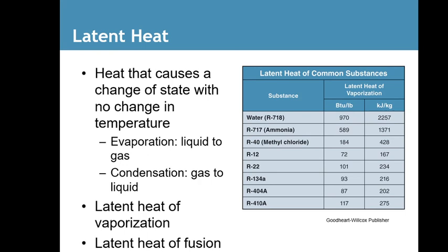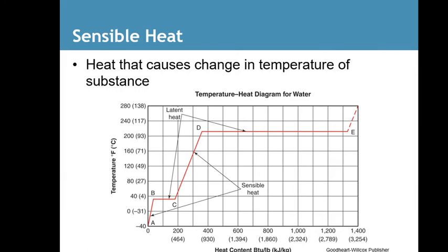Latent heat is the heat required to convert a solid into a liquid or vapor, or to convert a liquid into a vapor, without a change of temperature. Another way to say this is the quantity of heat absorbed or released when a substance is changing from one state of matter to another. For example, the ice cube sitting on a table will change state using latent heat. Sensible heat is the heat that can be felt as energy is moving from one substance to another.